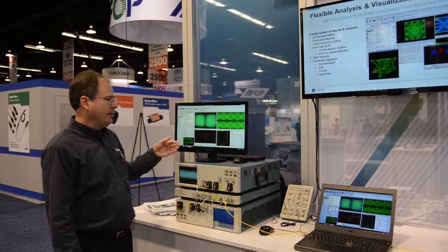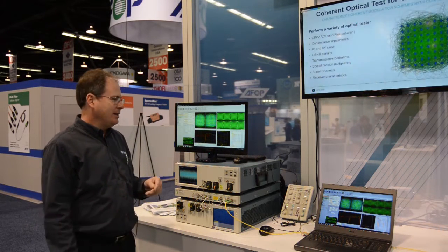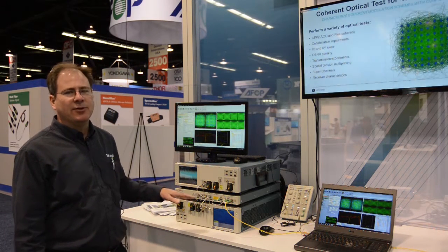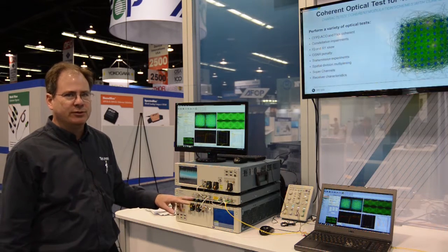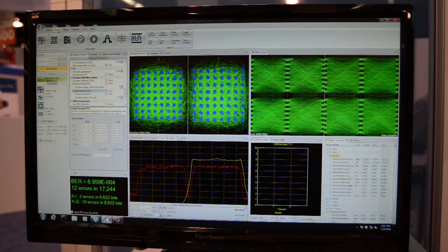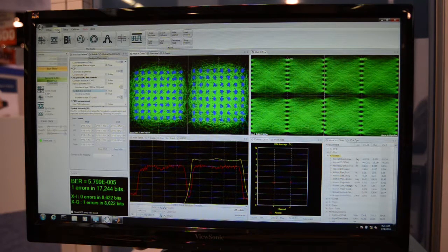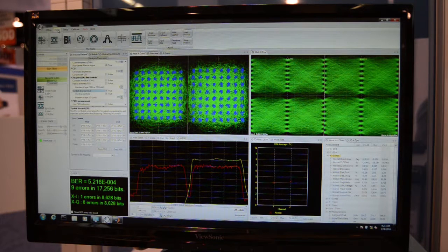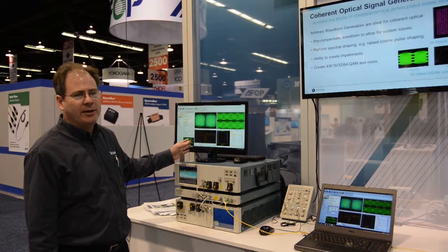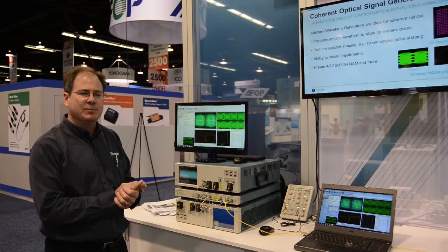The other thing we're showing here, in addition to the strong receive side equalization, is the multi-carrier capability. So we're not just receiving one 64 QAM signal, we're receiving two 64 QAM signals. You can see the two carrier frequencies here and here. So right now we're focusing on this particular carrier. We're selecting it with a digital filter, and then that's the one that's being analyzed, and this other one's being thrown away. But we have the ability to switch back and forth to analyze both carriers.